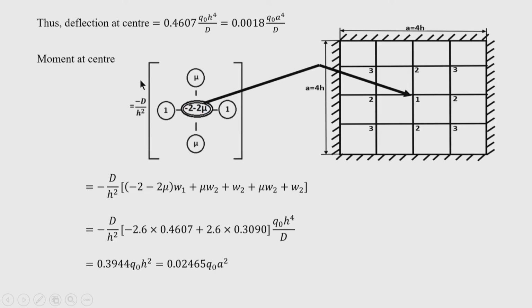Now, let us calculate the moment, because the second part of the question was to compute the moment at the center. Because of symmetry of the support and symmetry of the loading, we found that Mx equals My at the center.